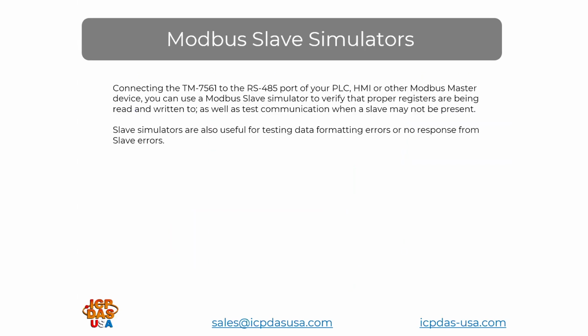Slave simulators do the opposite. Unfortunately, we don't have one, but there's a few out there. Specifically, just look at modbus.org, and there's some free ones and some that do a little bit more that you have to pay for, but they can be very useful. They also can be used with our TM7561 or i7561U to be a Modbus slave device or simulate a slave.